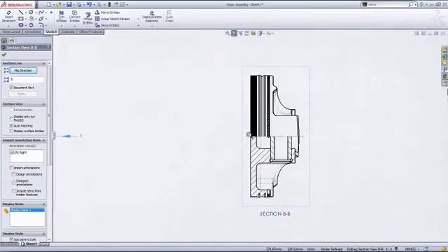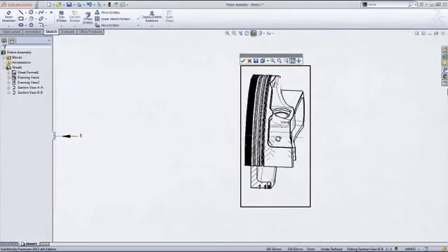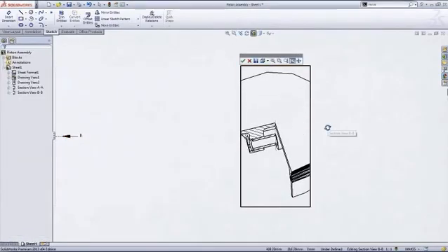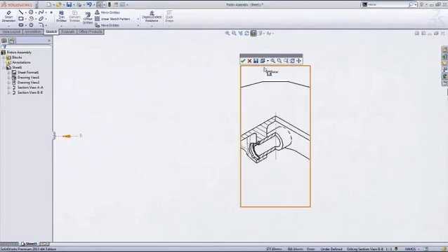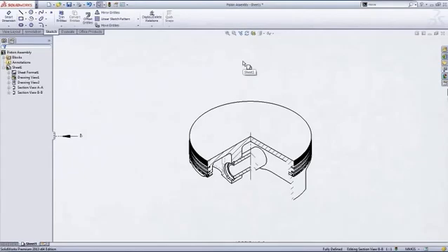view. To do this, you can select any view, and in the heads-up display in drawings, there's an option to rotate it. You can even choose predefined views in models like isometric. Then, if I click the OK button, the view will be saved in this position. Now, the line work in this view doesn't look that good, and this is the second part of this trick to make these look nice.